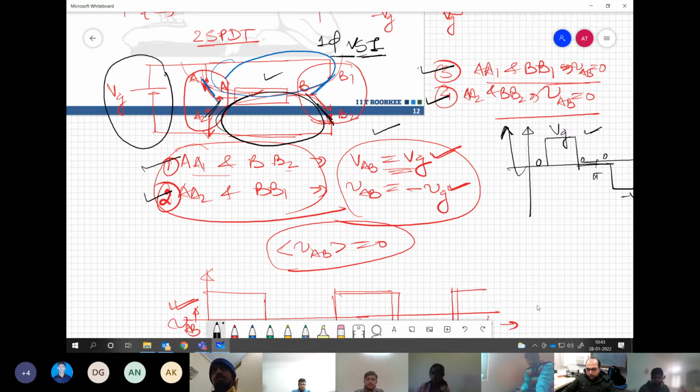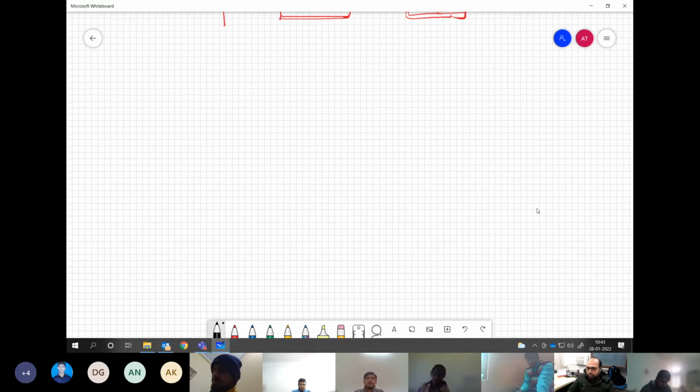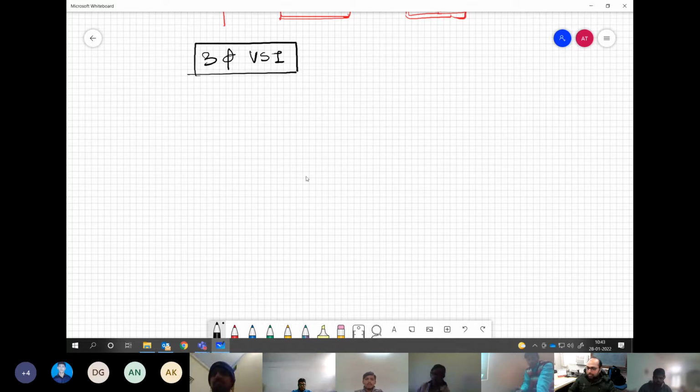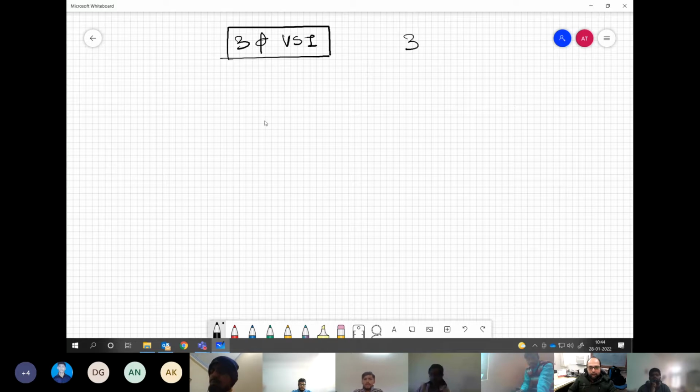Now, how many SPDT switches do we need for three phase VSI? 6. Okay, what if I say 3? Yes, sir. 3 is sufficient. So now instead of going by 6 SPDT switches, what we basically do in case of a 3-phase system is we realize the output on a per phase basis.